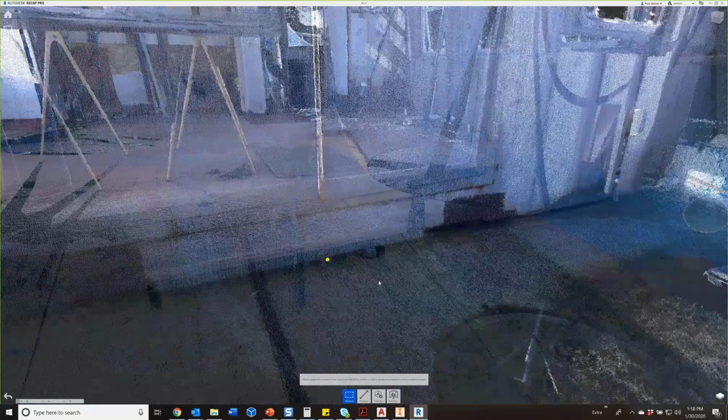And then basically you read the instructions down here on the tooltip. It says click to update the location, enter to confirm, or tab to update the coordinate directions. So if I click the tab button, I can go through and set up Z and X. So Z, the upwards direction, is usually already set by the scanner.